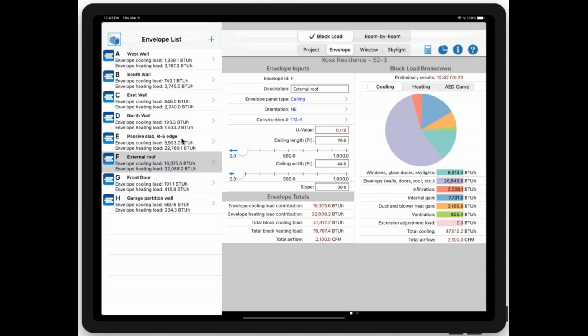Yeah, but then you've got the loss for the studs and all of that. So most walls have an outside insulation, which is continuous, so that's the full R value. But the wall cavity insulation would be reduced by somewhere around 25% for the frame. Yes. So you would have to do your own math there then. Okay, good. Thanks.